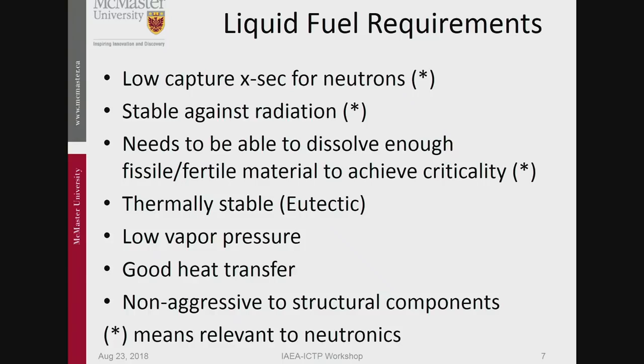You do not want that when this stuff cools down, the uranium says, oh okay, I'm going to solidify now, and then boing, drops to the bottom of your reactor. Because then all kinds of terrible things may happen. So it's very important that your liquid stays at this point here, where the two components melt at the same time. There's no precipitation of anything.